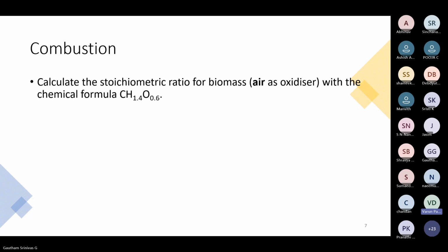O2 plus N2. How is that O2 plus N2? You have 1 mole of oxygen and 3.76 moles of nitrogen in air. So what is the chemical formula? O2 plus 3.76 N2. Yes. So instead of O2 in your equations from the previous lectures, you replace it with O2 plus 3.76 N2. Get it?